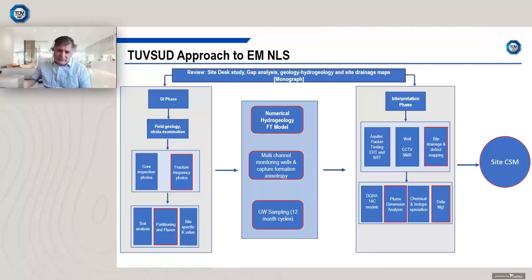And this is particularly quite useful in capturing the anisotropy of the water-bearing formations, particularly with sites with large concrete covers, because generally large concrete covers are influencing what I call, they create temporary hydrogeological features on site without naming anything specific. And in addition, we have shifted from carrying out 3 rounds of monitoring, but we go for constant, continuous monitoring now, obviously with the approval of the client, and it's got a significant expenditure from the client side.